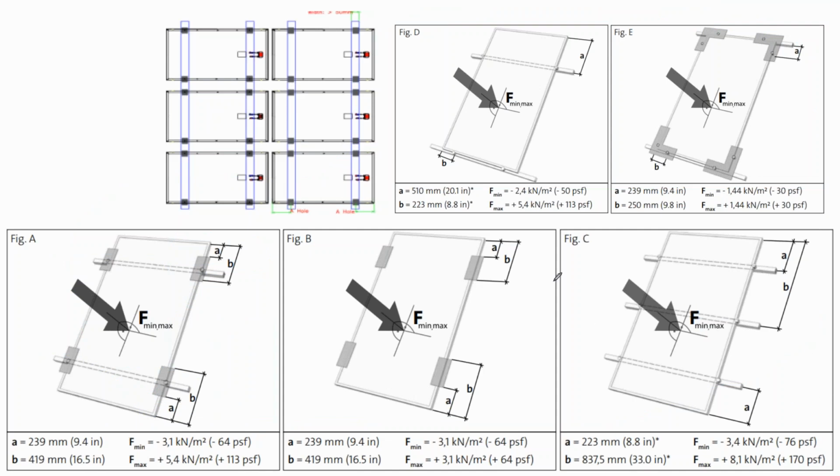For example, out of all these options, the strongest one is putting an additional rail behind the panels. That makes sense, giving it some more reinforcement. And that would be a technique you could use in, say, Florida to meet your hurricane zone requirements.